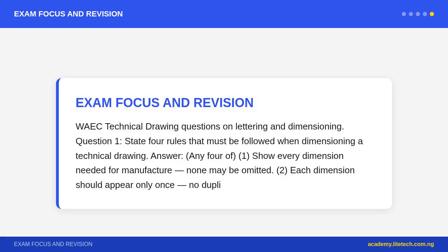Question 2. A drawing shows 4 times diameter 12. What does this notation mean? Answer. It means there are 4 circular holes, each with a diameter of 12 mm. The symbol denotes diameter, the prefix 4 times indicates the number of identical features.